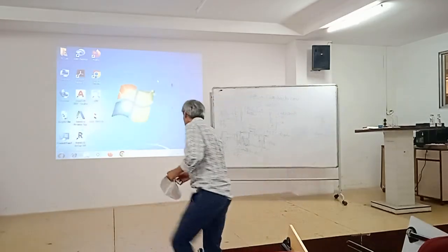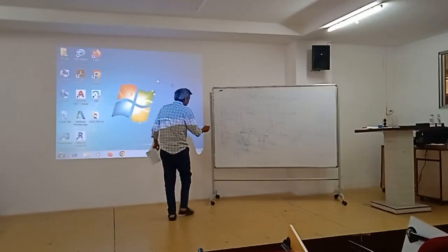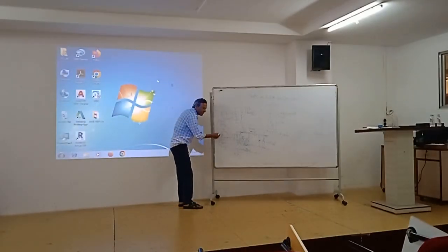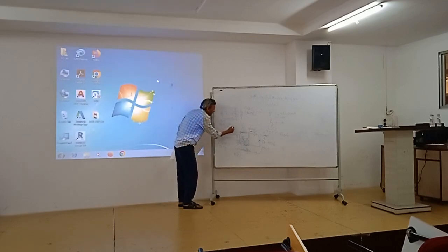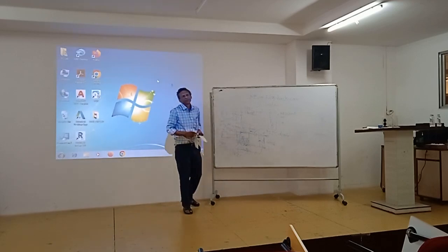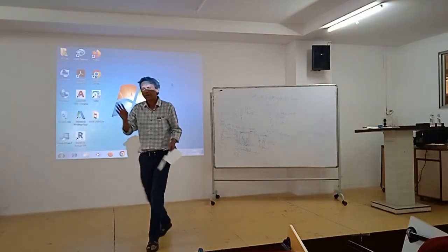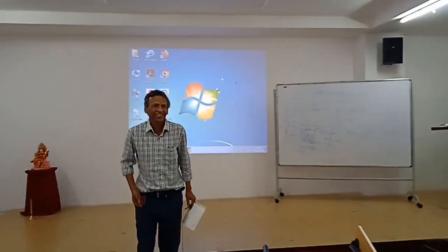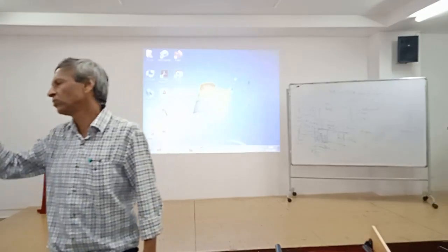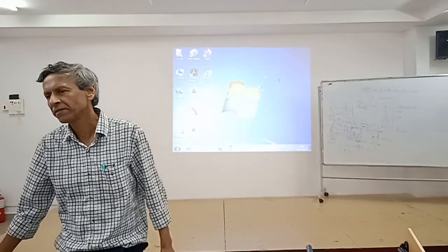But from the utility side the problem is removed. Utility will put a meter here and say PF is almost 0.999 and THD we reached about 6%. We told the madam that the current THD does not come to 5%, it stays 5.5-6%. Even my knowledge in those days was not that good.